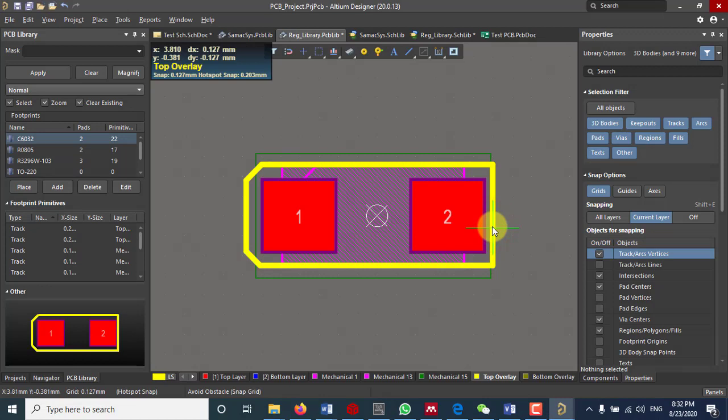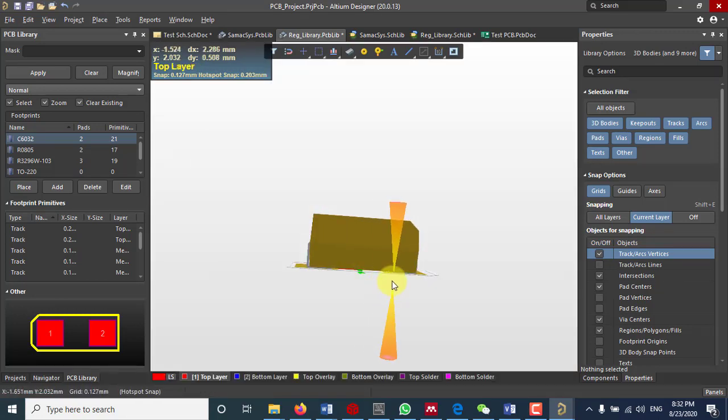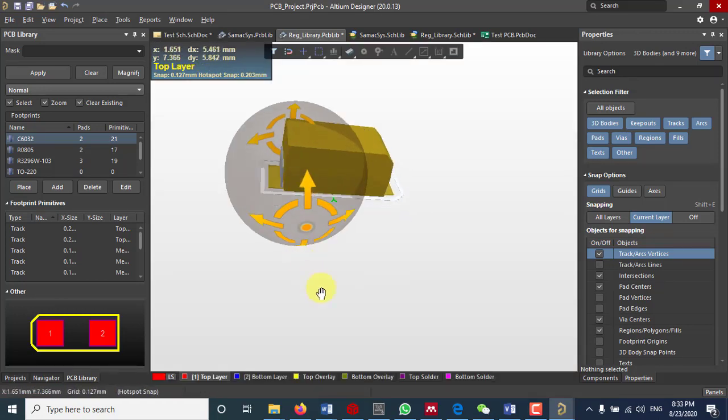So you can make those fine tunings just by dragging these lines, because they'll just print on your PCB. There is no strict constraint on the dimensions. So you can use this technique of dragging corners to make it look better. Alright, you can press 3 to view it in three dimensions.